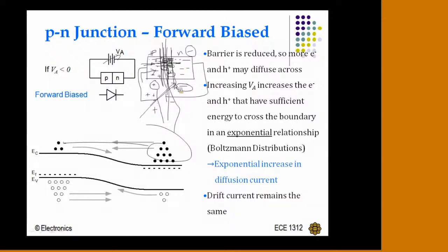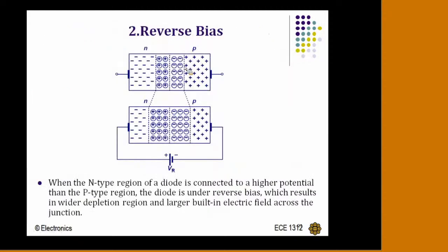Now this is the main reason, the forward bias due to the external voltage. Majority electrons are moving from one region to another region, and that constitutes the current, which is the diffusion current. In forward bias, the maximum current will conduct, and that current is due to the abundant charge carriers. Now come to the reverse bias. Reverse bias is a different scenario. Now what is the reverse bias?